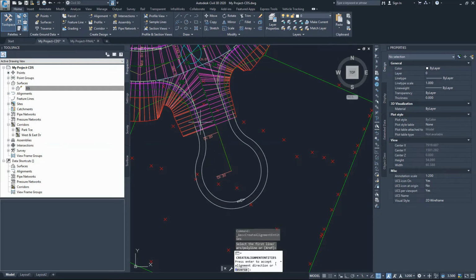It doesn't matter really, it doesn't have to match any of these directions, but it's important to know your direction. So by knowing the direction, as we agreed, I will know which assembly to use. Knowing the direction going this way, that means if I am driving along this alignment, I have to choose a cross section where I have the lane on the left hand side and the sidewalk and daylight on the right hand side, so the right hand side assembly. So I'll accept that direction,